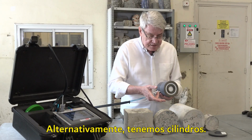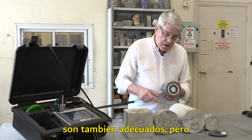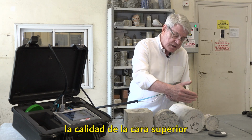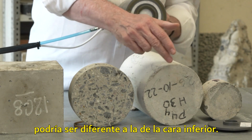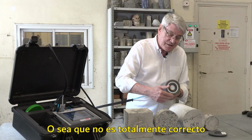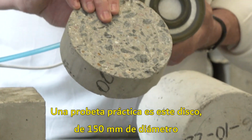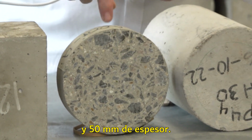Alternatively, we have cylinders. The cylinders of 150 millimeters diameter are also suitable, but we have to consider that in a long cylinder, the quality of the top surface is different or might be different to the quality of the bottom surface. So it is not totally correct to mix data obtained on both faces. A practical sample is this of 150 millimeters diameter and 50 millimeters thickness.